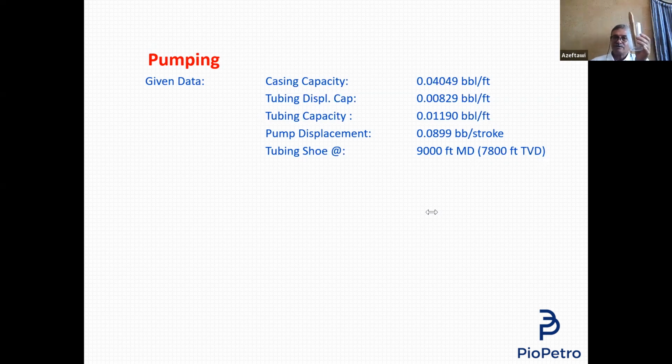450, of course. It was 500. 50 barrels are out due to the fluid displacement volume. What's the remaining? It is 500 minus the 50 that went out, so it is 450. The total volume of this well is 450. People who said 500, you will never see 500 again as long as the production tubing is inside this well.